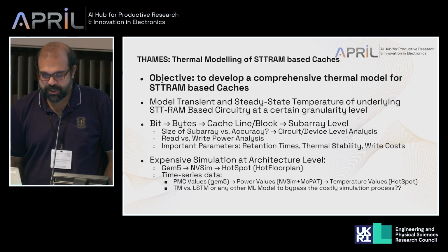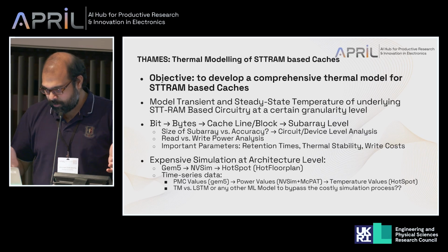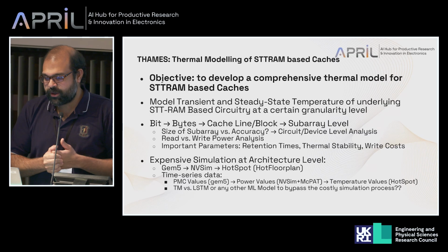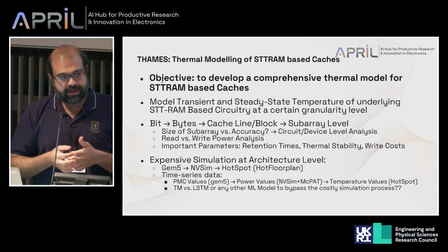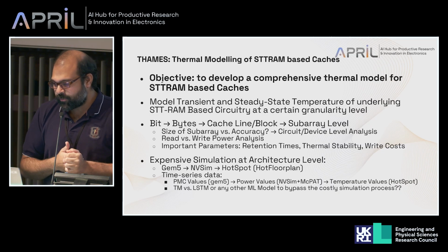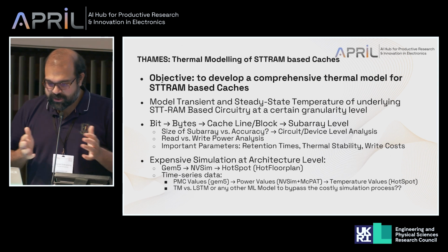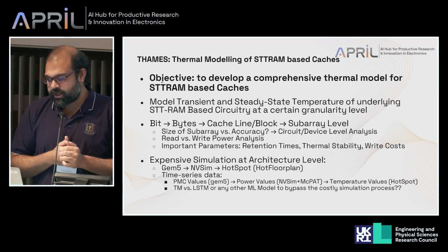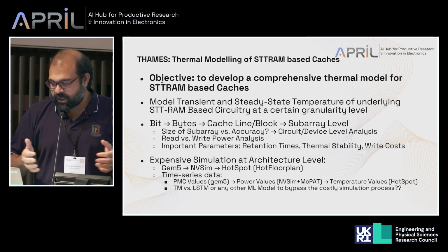The primary objective of this initial part of the work is to model STT-RAM in terms of temperature. That is thermal modeling of STT-RAM or magnetic RAM-based cache memories, and the short form of this name is THEMS. The objective is to develop a comprehensive thermal model for STT-RAM-based caches, where we have started by modeling transient and steady-state temperature of the underlying STT-RAM-based circuitry at a certain granularity level.